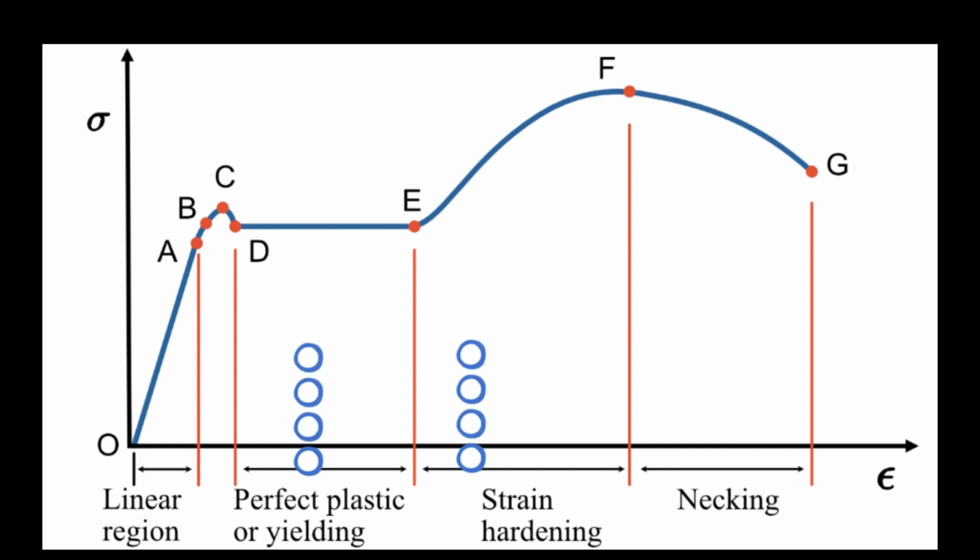In this region, 1. The strain increases with a significant increase in stress. 2. Elongation of the bar is due to the slippage of material on an oblique plane. Hence, shear is responsible for the elongation. Elongation due to shear will not lead to any volume change. 3. Hence, there is no volume change during plastic deformation. Note, shear stress is maximum on the 45-degree plane.